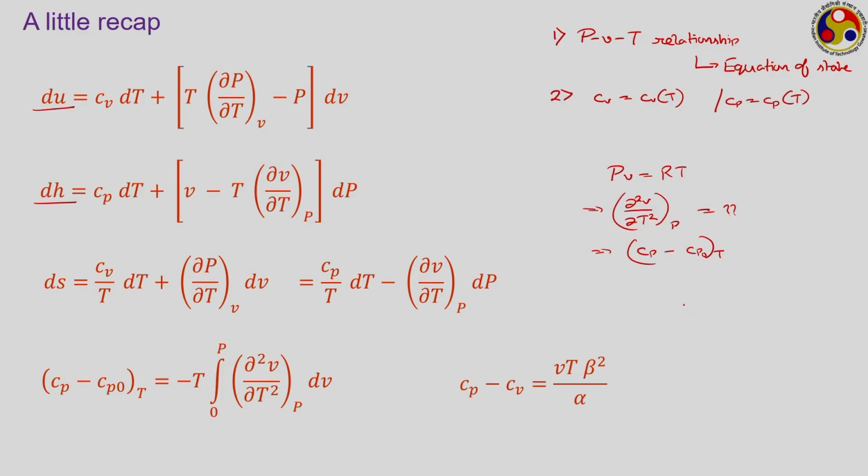Of course, being quite similar to enthalpy, a combination property, you can simply use its definition. So, suppose you are looking to calculate F2 minus F1, that is the change in specific Helmholtz free energy during a particular process. Sometimes this is written as F12, which represents the change in value of F from 1 to 2. So, we know what your F2 will be. F2 will be U2 minus T2S2, minus F1, which will be U1 minus T1S1.